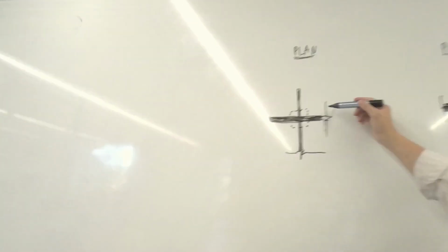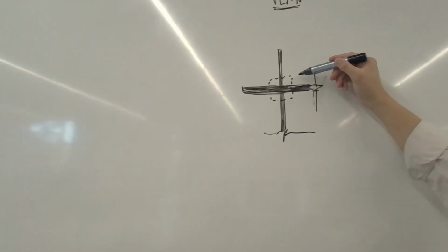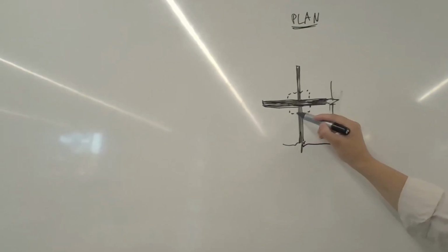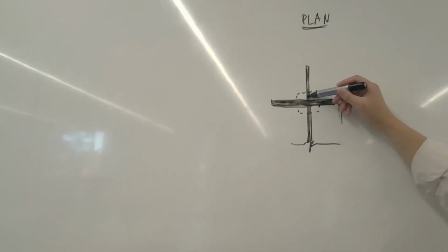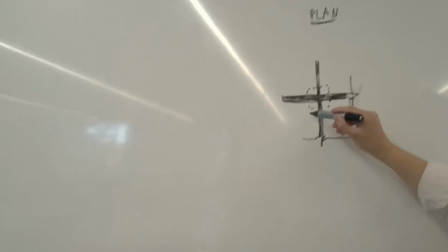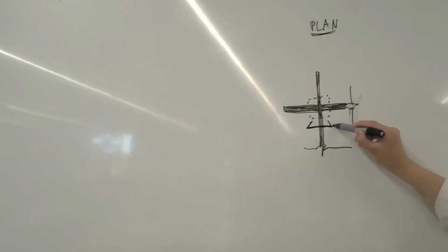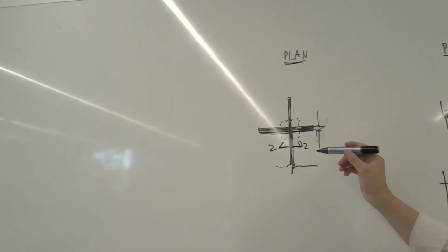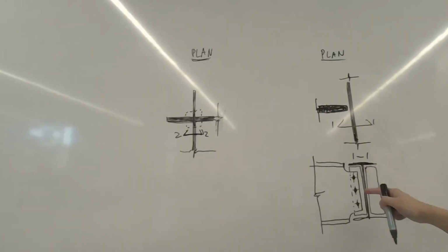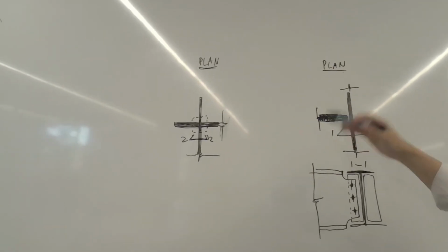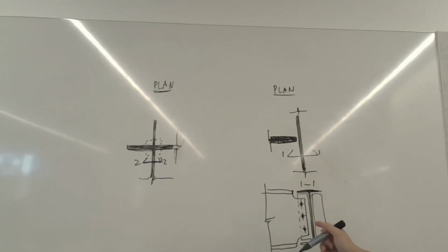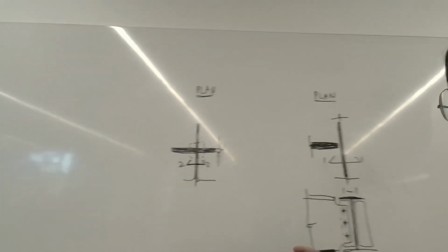So that dashed line is basically saying, I want you to draw that detail, the plan view detail, and then later once we've gone through that, I want you to draw the elevation detail, section 2-2. So I want you to draw the detail top down first, and then the elevation. Think about what this needs to look like so that it can resist those rotational forces, because this currently doesn't resist any rotation, on paper, from a mathematical point of view. So you guys just give that a go.